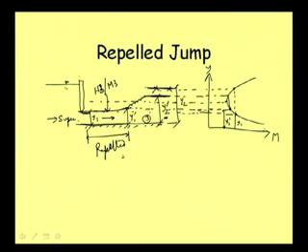And that way, when we have a very low downward flow, but it is subcritical, of course, the jump will be there, but once the jump is there, then only energy will be dissipated at this point. Energy will be dissipated, and once energy is dissipated on the downstream side, we are getting less energy, or we can say that the flow will not damage the downstream part.